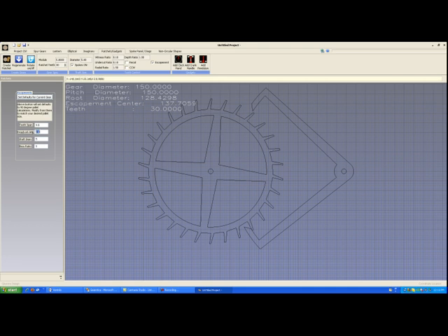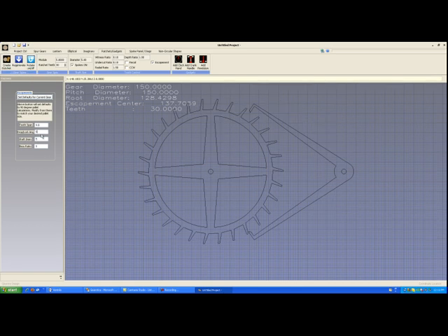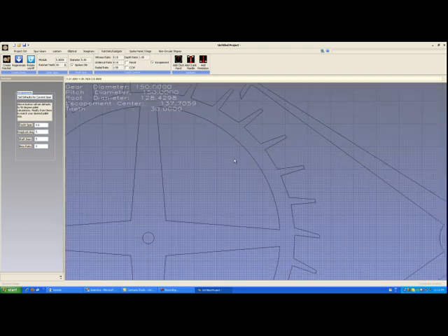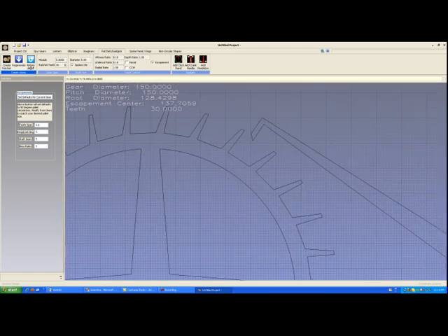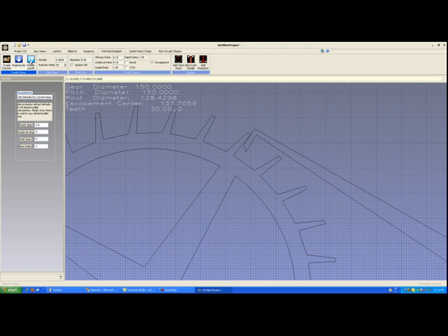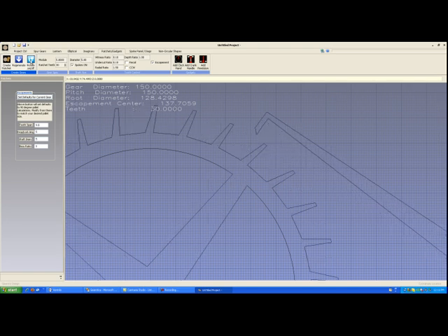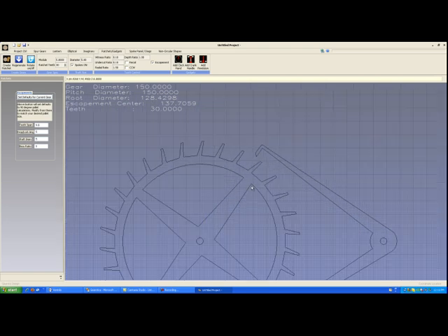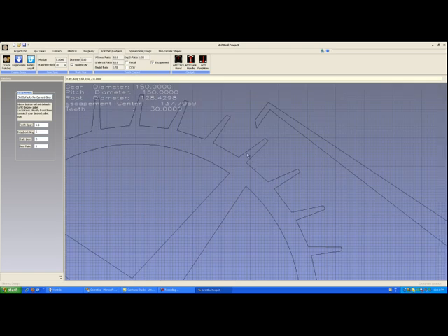If we change this drop lock angle, for example, to 5 degrees, just as a test, and we hit regenerate, you have to hit regenerate if you change any numbers on the left. You can see what's happened. The pallets have gotten very short, and as we swing up and we jump, you see that the jump that we just made was a much larger angle. It may even be around 5 degrees. I haven't actually measured what any of these drops are, but you can see two problems.